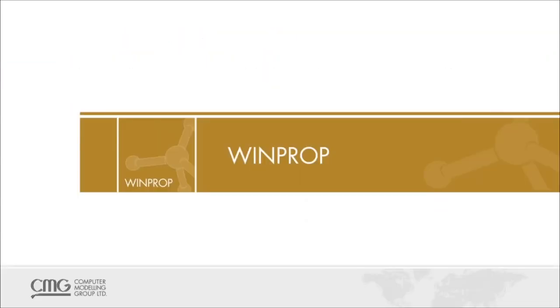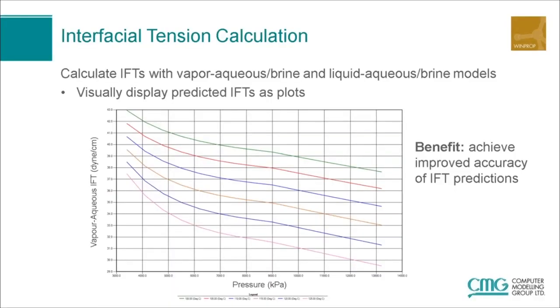Next, we'll talk about some of the improvements to WinProp. So I mentioned earlier, we have several improvements that have been introduced to GEM recently, especially around chemical EOR and aqueous phase modeling. And so WinProp has been upgraded as well to be able to better assist users in generating the simulator inputs that they require for these GEM processes from the lab data that they might have.